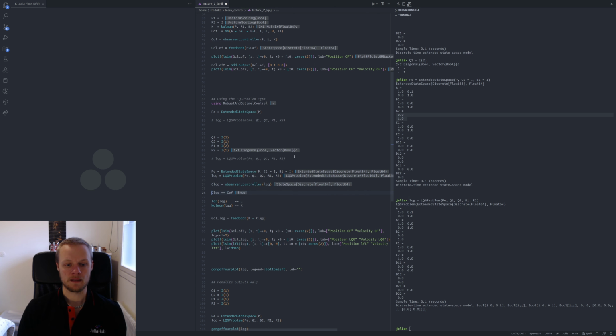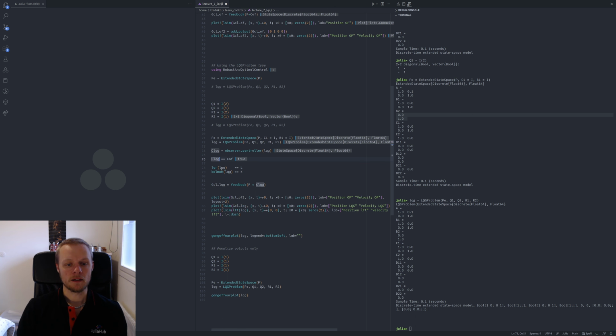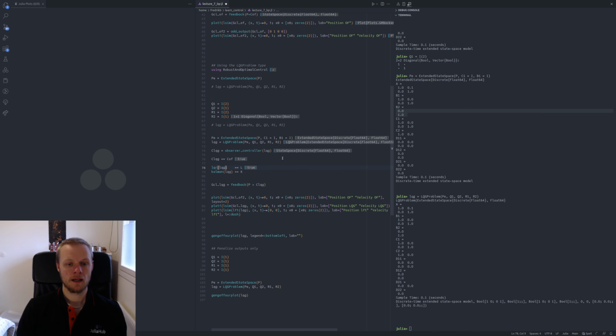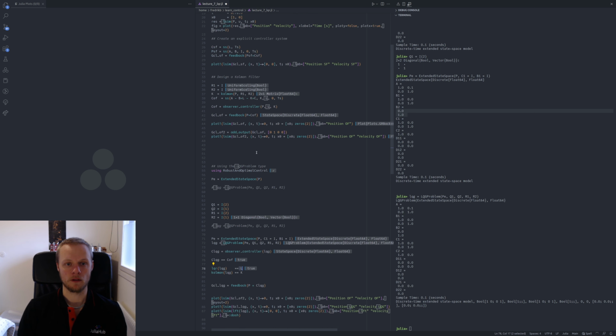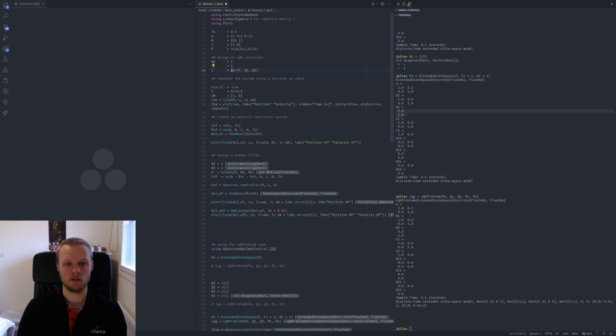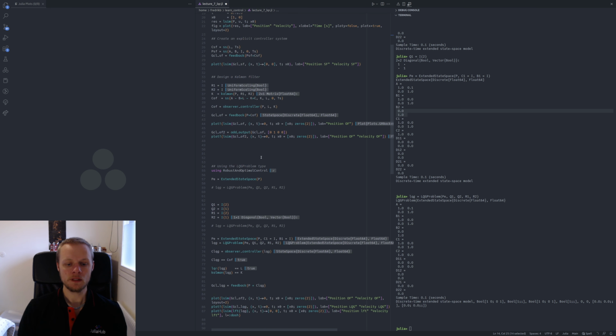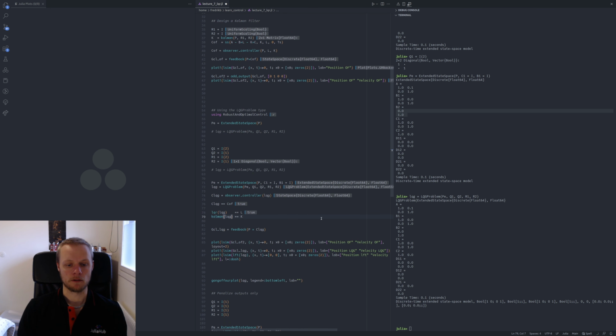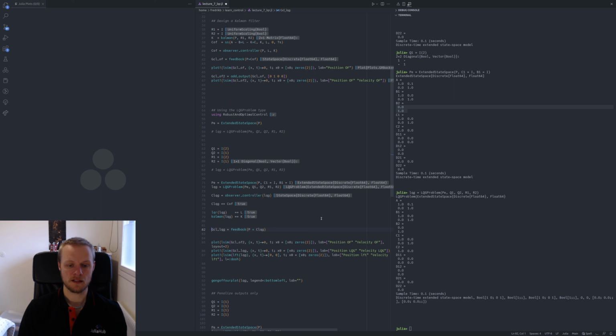And we can see that it's identical: COF is for output feedback, the controller I created above, and LQG is the controller I created now. They are equal. I can also ask what's the LQR gain of this LQG struct, and that's identical to the gain I computed by the explicit call to LQR here above. All right, and similar for the Kalman gain, they're also the same.